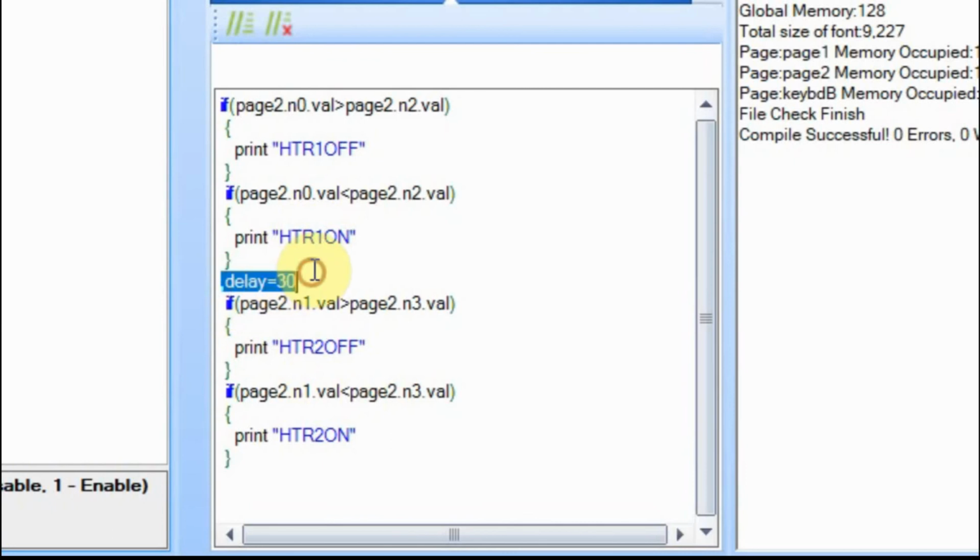And then we need a short little delay. Otherwise it's going to smash these things together because it's going to send this or it's going to send this. And what happens sometimes in the Arduino, if you send stuff too close together, it can get a little confused. So we're just going to put a 30 millisecond delay in here just to make sure we keep some separation. It may work without that. You can play with different delay lengths on your own if you want, but I found that it's helpful if you're sending two strings to have a little bit of a gap between them.